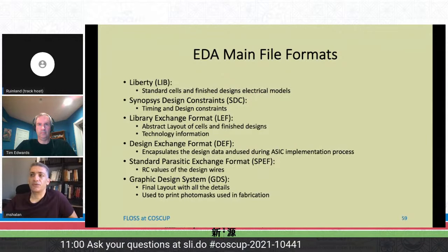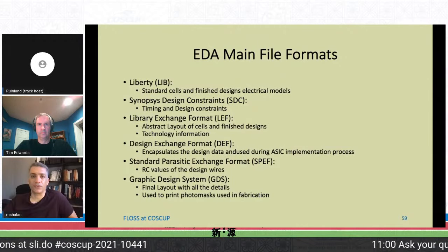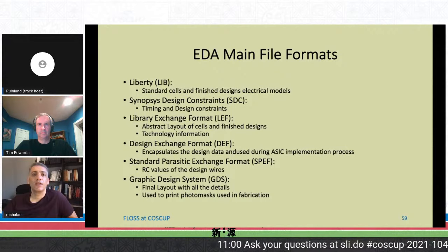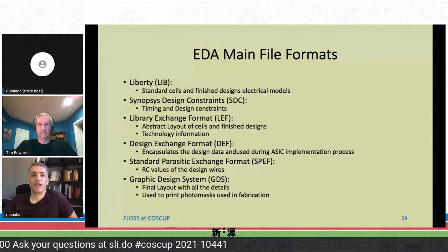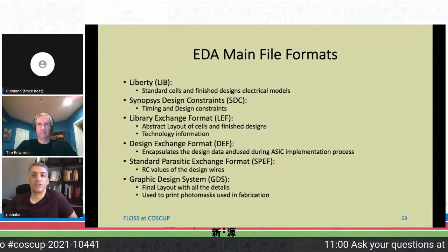SDC, or Synopsys design constraints, is used to capture the timing and design constraints, also a text file. Library exchange format, or LEF, has an abstract layout for the cells, and also an abstract layout for the finished design, as well as technology information in a special version of the LEF file called the technology LEF.